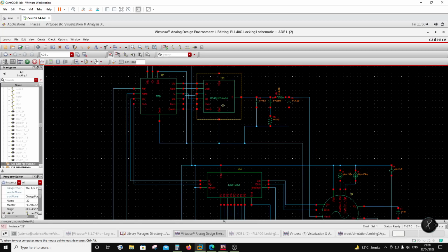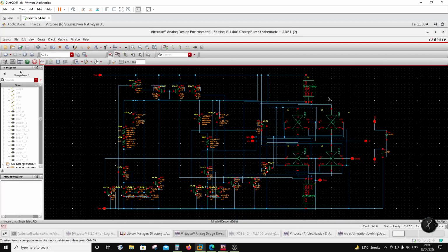Now, if I go in here, this is similar to the previous charge pump on the right hand side. CC bar are not being used, so they are just terminated into caps. I didn't bother to throw them out. What you see over here is a PMOS wide swing cascode current source, which has high output impedance, which we have seen earlier also.